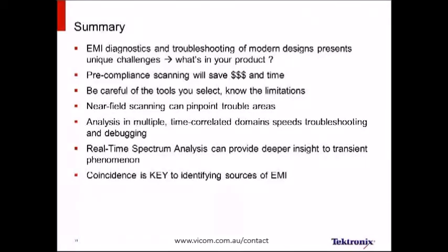Analyzing the data from a time-correlated perspective, meaning looking at analog, digital, and RF simultaneously, will speed up our troubleshooting and reduce our debug time. Coincidence is the key. If there's one takeaway from the whole talk on EMI measurements, it is that coincidence will help us find the source of EMI problems much, much quicker.